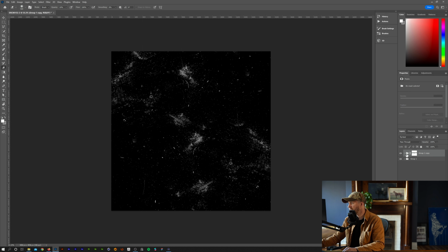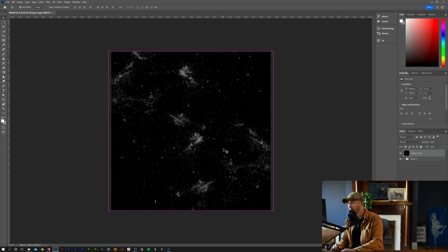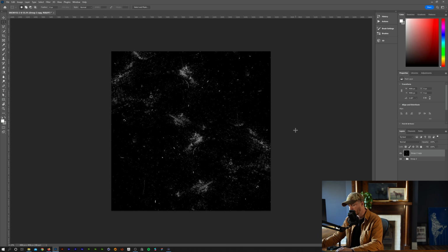So what we need to do is we're just going to grab both of these groups now, group them once more, Control J to make a copy of this, and then you want to hit Control E on your keyboard to rasterize that second parent group. So now we have this as one single image, which we're going to use. Now to make sure that this is cropped again, because that original image size was a little bit wider than our 4096, on your keyboard, hit Control A to select all, and then come up to Image, and we want to hit Crop. So now this image should be cropped, which is exactly what we want for creating seamless textures.